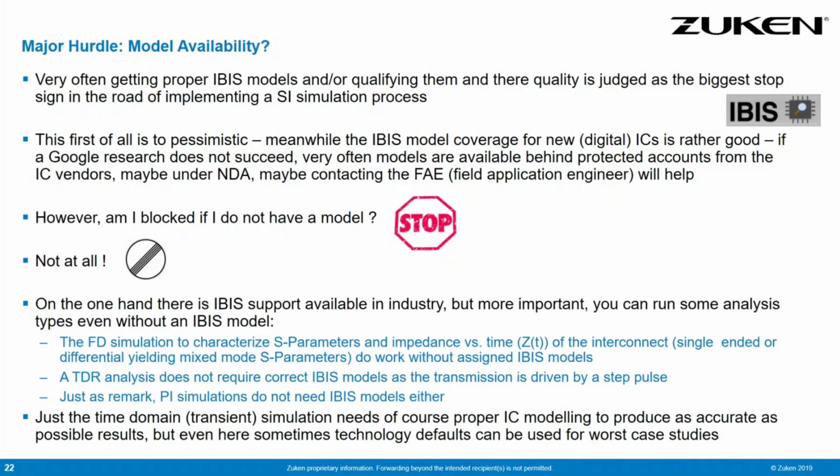And another important thing to mention: I did mention these different kinds of simulation methodologies for frequency domain simulation and as well for time domain TDR analysis. You don't need IBIS models. So you can perform such simulations without having models for the active components assigned. You need models for a transient simulation, figuring out the real interconnect timing, to figure out whether setup and hold requirements are met or violated.